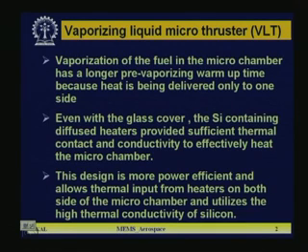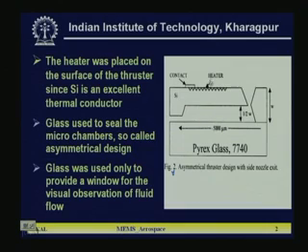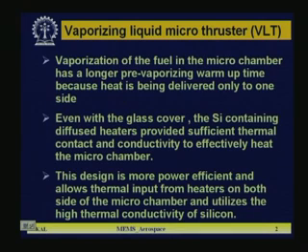Why one side? Because the heater you have put in one side only, in the silicon here, not in the bottom side. Bottom side is only glass. So, that side you have to give some warm up time, so that the complete thing heats enough to change the phase of the propellant from liquid to gas. So, now even with the glass cover, the silicon containing diffused heaters provided sufficient thermal contact and conductivity to effectively